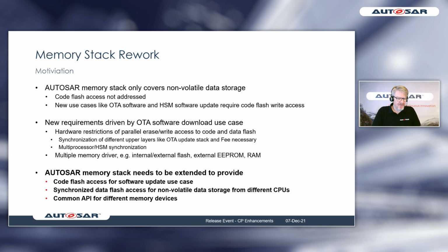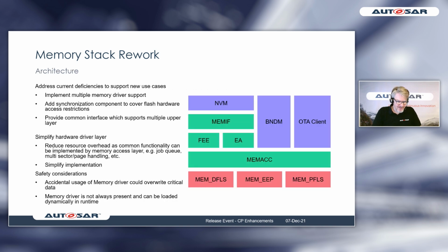Also on SOC devices, we have multiple CPUs, or a hardware security module, accessing the flash in parallel. So we need synchronization mechanisms and also more demands for a common API for different memory devices. So what is done in this rework?